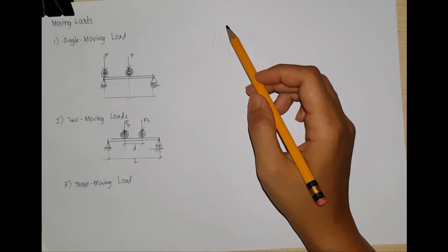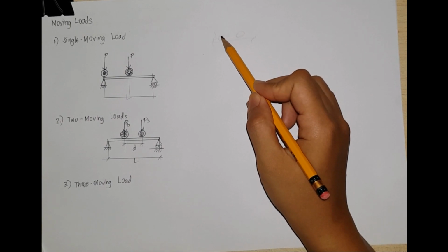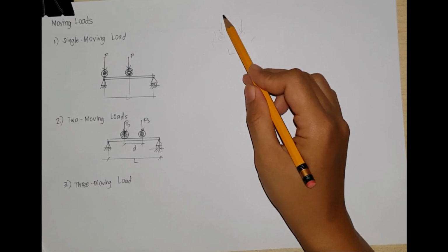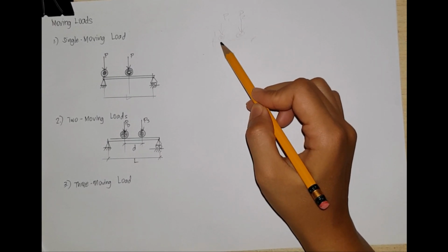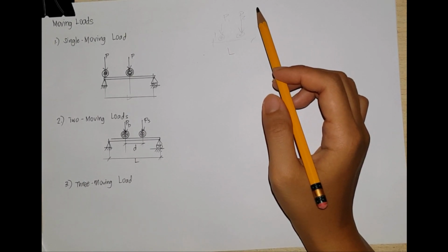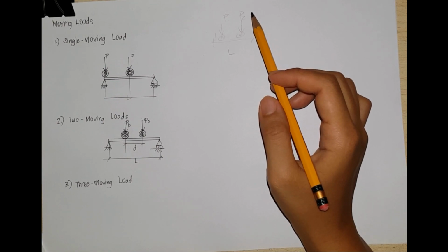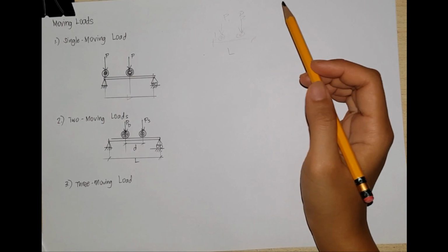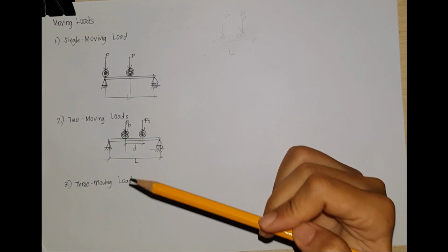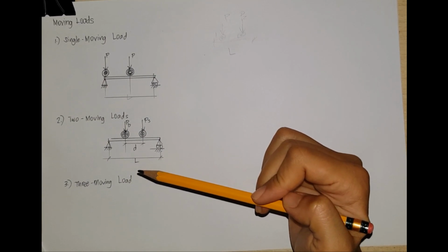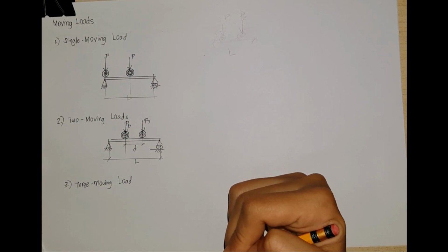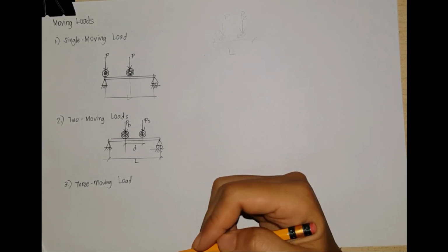with a moving concentrated load. So for example, ito yung mga gulong ng sasakyan. It has a certain load which is moving all over the span. So the problem here is to determine the moment under each load when each load is in a position to cause a maximum moment. So from our previous section, we see that the maximum moment occurs at a point of zero shear. And for beams loaded with a concentrated loads, the point of zero shears usually occurs under a concentrated load, and so the maximum moment.